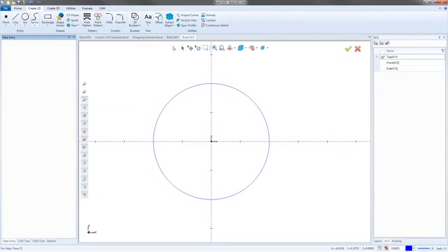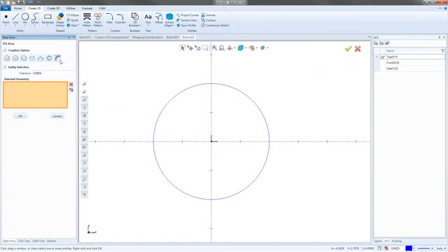I'm going to go to Arc. If you want to go directly to the fit arcs without opening the arc menu first, you can click the drop down at the bottom. All these little arrows are drop downs. We could say fit arcs. I got fit arcs. Now right here is my tolerance.